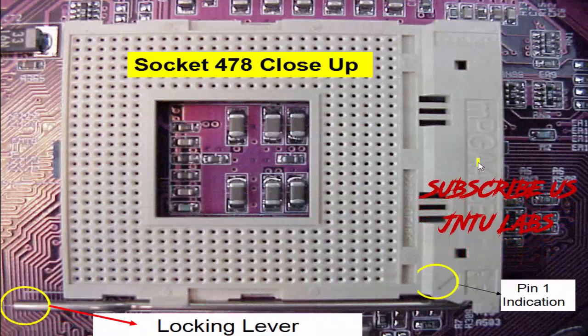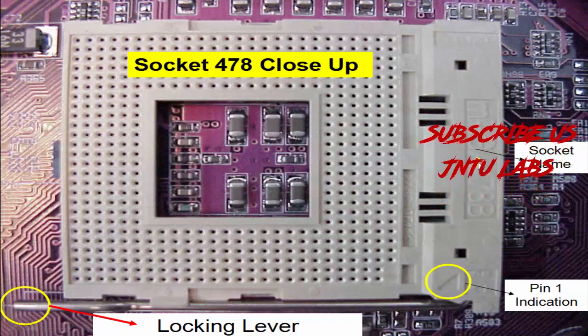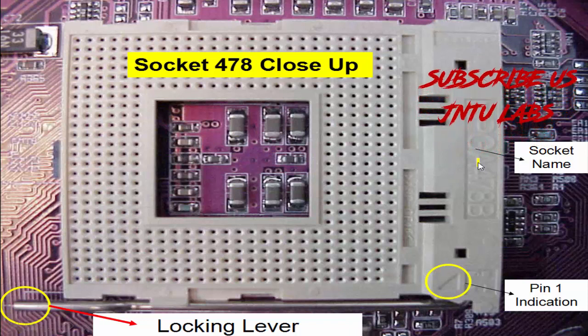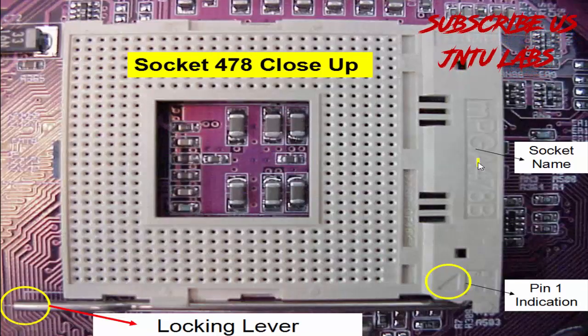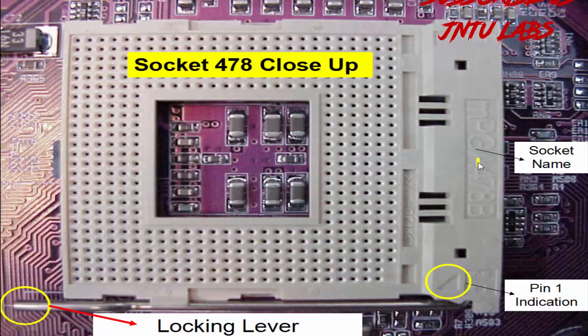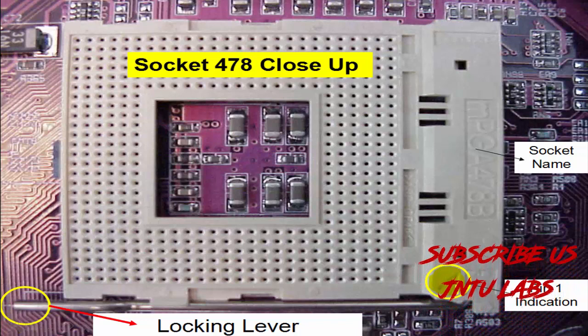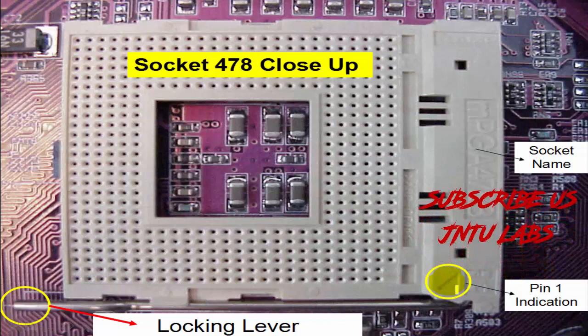If you take a close look, there are notches and the socket name, also 478, and a pin indication. Whenever we place the CPU on this socket, we must always check the pin indication. See here, we have a pin indication. So it is very important to look at it and then place the CPU. And the locking lever is very important to lock the CPU, else it can burn out.